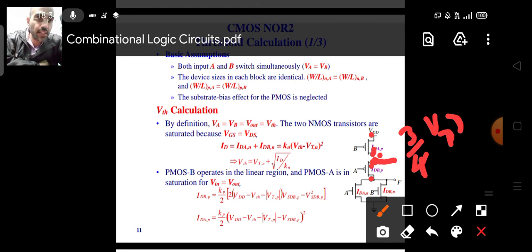So this is VTH and that is also VTH. So both the inputs, see, drain is at VTH, gate is also at VTH, source is at 3/4 of VDD. So you see, both VGS is equal to VTH. So the lower PMOS will work in the saturation region.